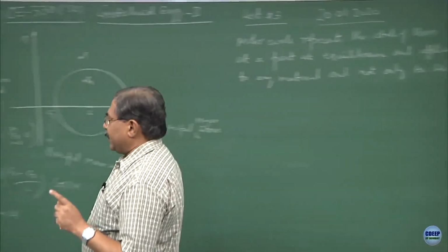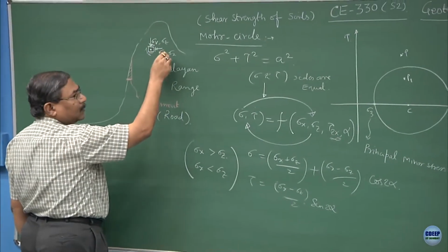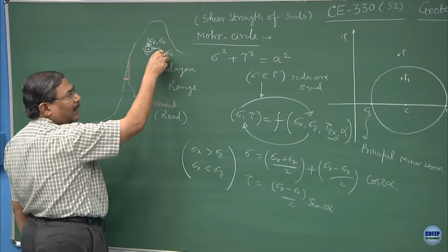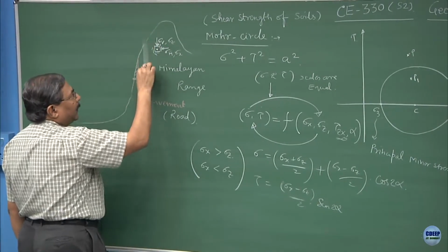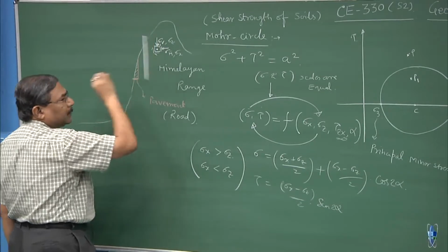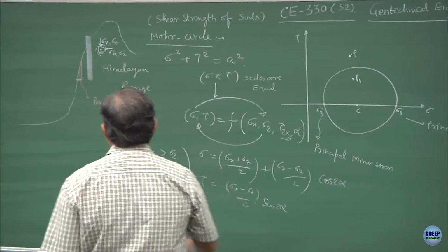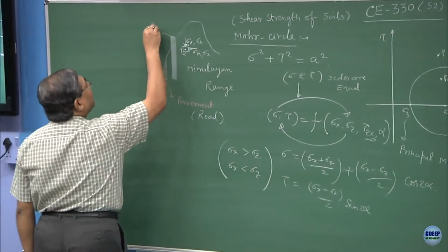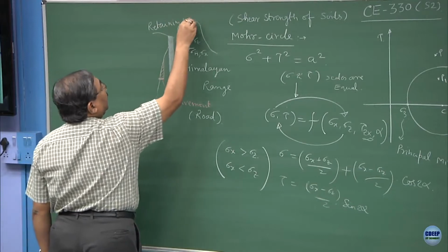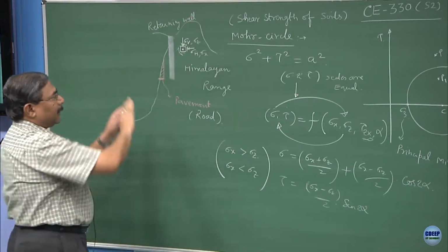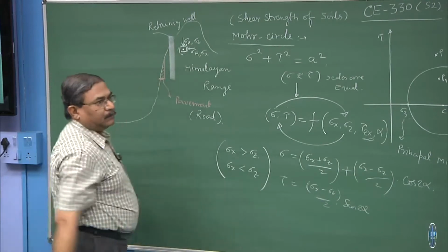Now, common sense says if the vertical stress is more than the horizontal stress, I still require some confinement over here, this becomes a retention system, which we will analyze. So, this becomes a retaining wall. You must have seen when you move around hilly terrain, they try to stabilize the entire slope by putting a retention scheme. So, this becomes a retaining wall.